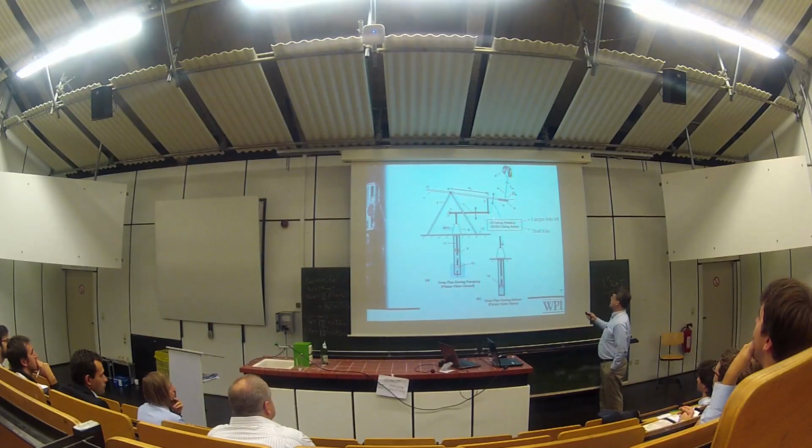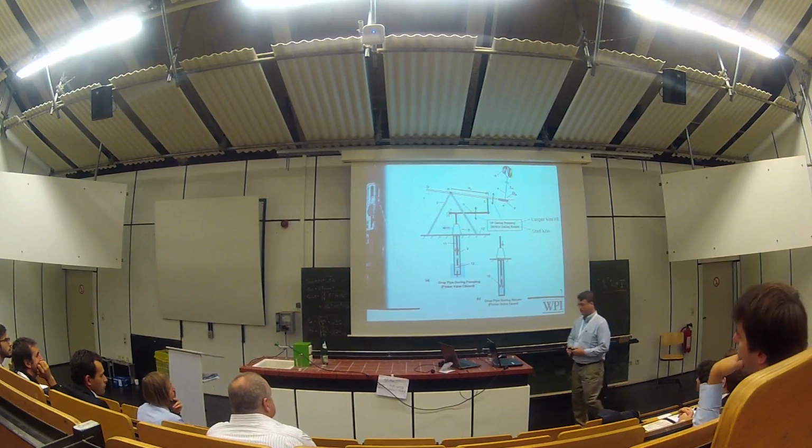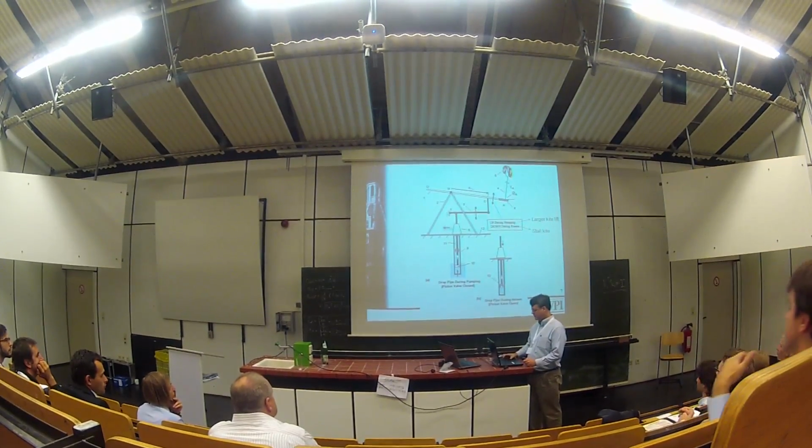During a pumping phase, if we have large lift on the kite and the kite is moving up, of course the arm moves up, again transferred through the linkage. This is a simple displacement or lift pump, driving upwards with a valve closed down here, and we pump water out. To bring the arm down, we stall the kite. Lower lift forces stall the kite and create a periodic motion. Very simple operation.